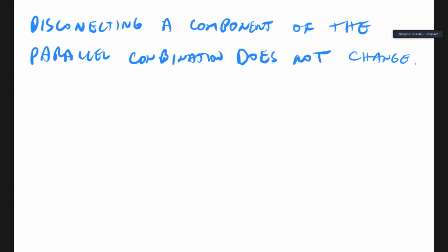So when you're looking at just the natural response, which would be the step response, not the steady state response, it doesn't matter which one you are driving, it always looks like the same parallel combination, and that natural response does not change.